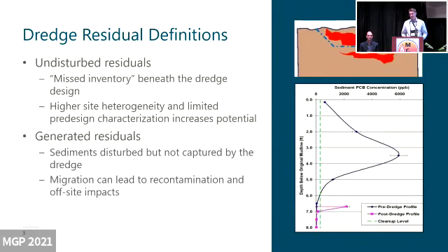And that's the result of just the sediment that was dredged, that as the bucket goes up through the water column, it falls out of the bucket and deposits back and creates that post-dredge surface as sort of a fluff layer that has a concentration that's representative of everything that was above it. So you can see that it's sort of an amalgam of these concentrations that were removed.